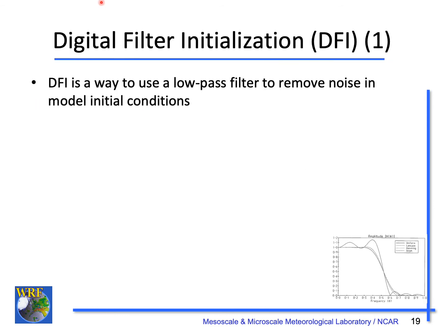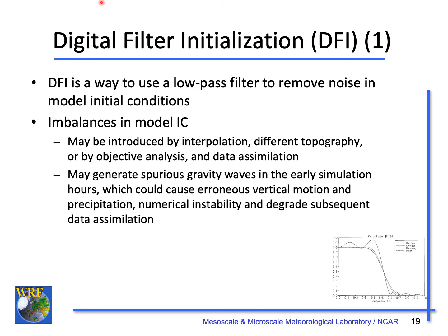The next option we're going to talk about is the Digital Filter Initialization option, or DFI. What is DFI? DFI is a way to use a low-pass numerical filter to remove noise or imbalance from the model initial state. Why is the model initial state not balanced?